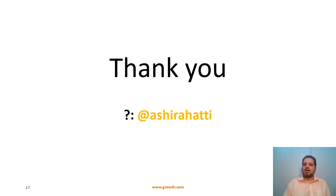There are different metrics. We need to look at multiple metrics to do the sign off, but from the coverage point of view, once these metrics are met and they're judged 100% values, you can sign off on them. So I hope this session gives you the fundamentals about the coverage metric. We have discussed the functional coverage through the cover group construct as part of this session, so that lays the foundation. Next we will look into the SystemVerilog cover group construct itself, which we have not looked at. Okay, thank you for listening.